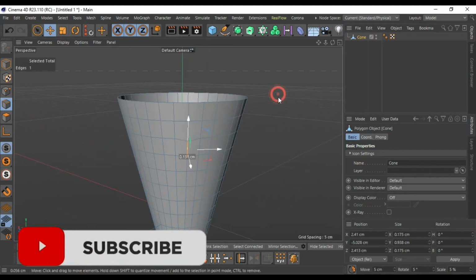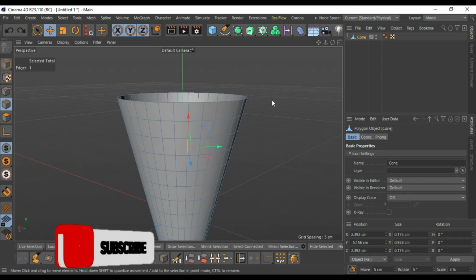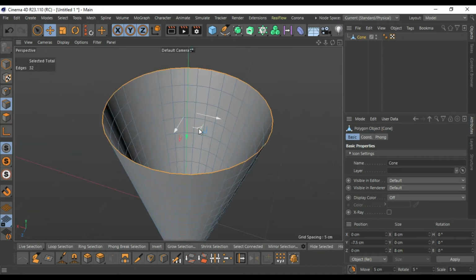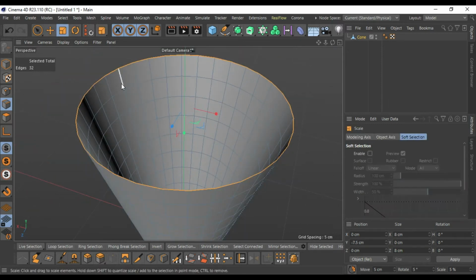So I think I need to double click on a ring, it will select the whole ring. Use the T key to scale it. Use the shift key and it will use the opposite two directions. This is the y axis, this is the x axis, and this is the z axis. So if I press shift on the y axis, the z and x axes will be used, same as if I press the x axis, the z and y are used. If I press the z axis, the y and x will be used.